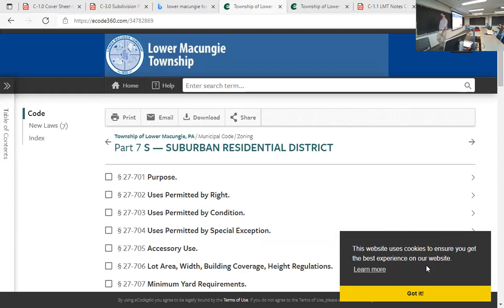One person was actually able to figure out that this particular municipality had a minor inconsistency. It's actually labeled 200 in one spot, but 225 feet in another spot for the center line radius. We're going to go with 200. Okay. Now that's the minimum.